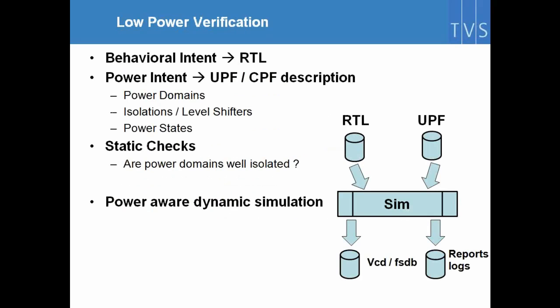So in terms of verification techniques, everyone is used to verifying RTL using simulations or formal techniques. The power intent is coded in UPF, so it's part of the design. The UPF is really part of the design. It's the power intent which is coded in UPF, and that needs to be tested. It contains the power domains, isolations, level shifters, power states, power transitions. There is a lot you could do in the UPF.